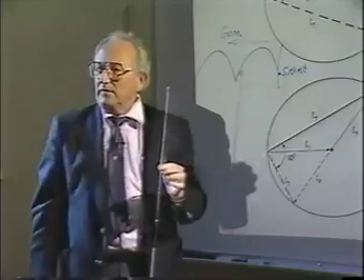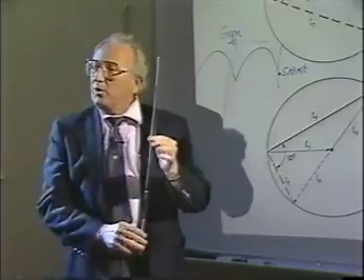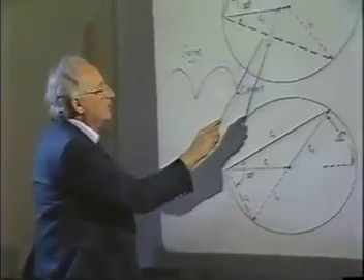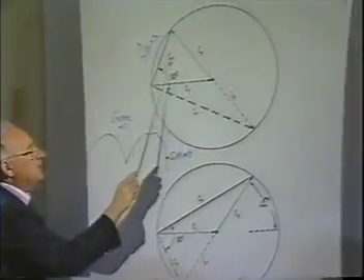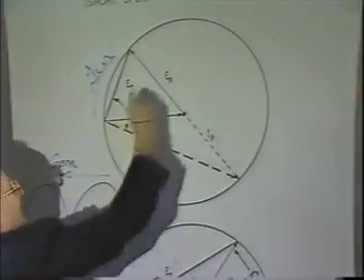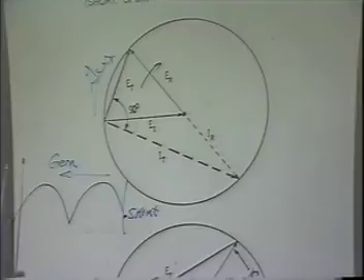Two signals are traveling. If I want to represent that by one vector, this vector here, E sub I, the incident signal, and I keep it fixed in position, then E sub R is this one, rotating in this direction here. Then it's going to have to rotate at twice the angle that any one signal is traveling.